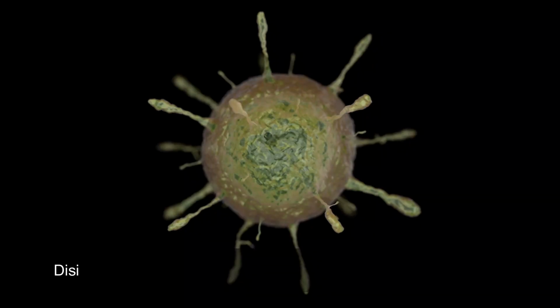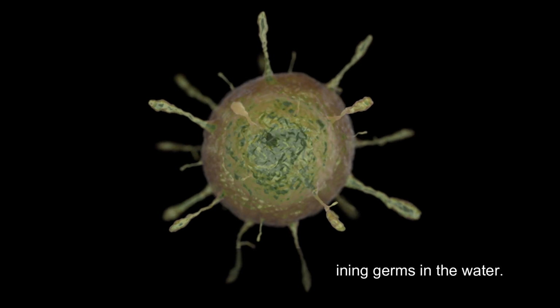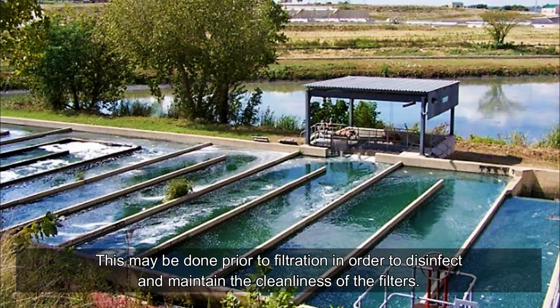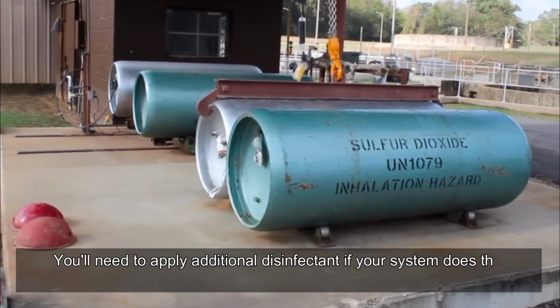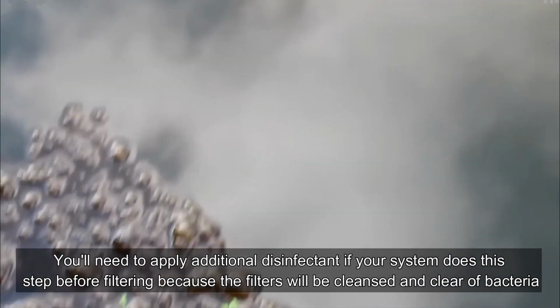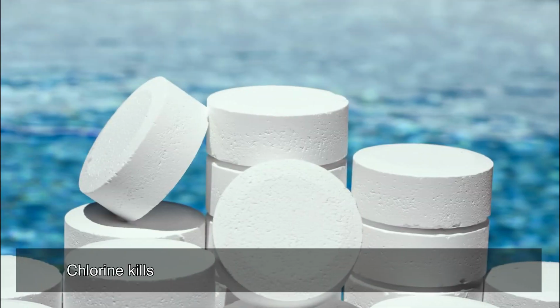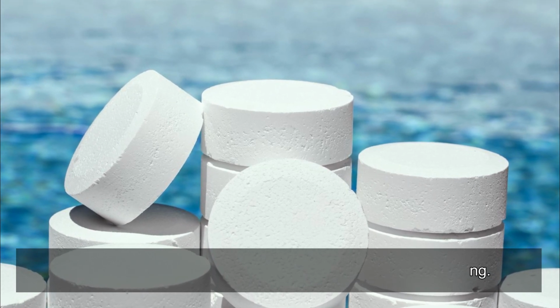Disinfection. Disinfection is used to get rid of any remaining germs in the water. This may be done prior to filtration in order to disinfect and maintain the cleanliness of the filters. You'll need to apply additional disinfectant if your system does this step before filtering, because the filters will be cleansed and clear of bacteria. Chlorine kills germs at the source, resulting in reduced fouling.